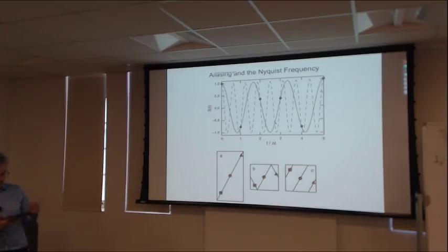And that's shown here. Here I have some wider spectral width. If I narrow the spectral width down, this peak appears artificially in the spectrum somewhere else. Where they end up will depend on how I did my quadrature.